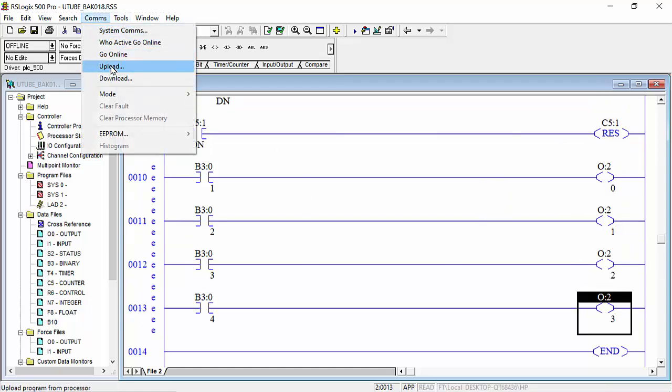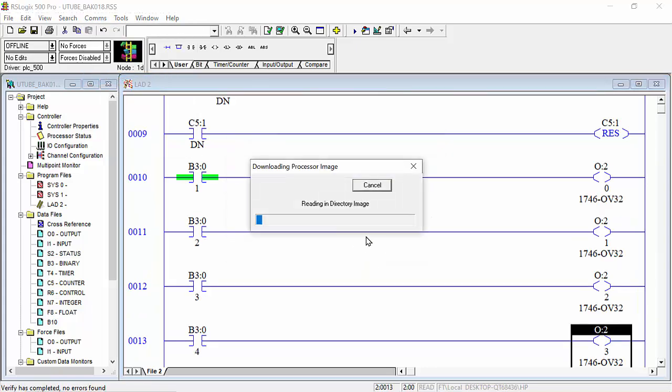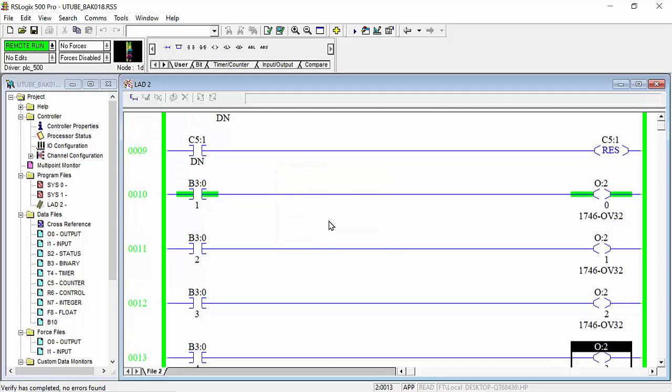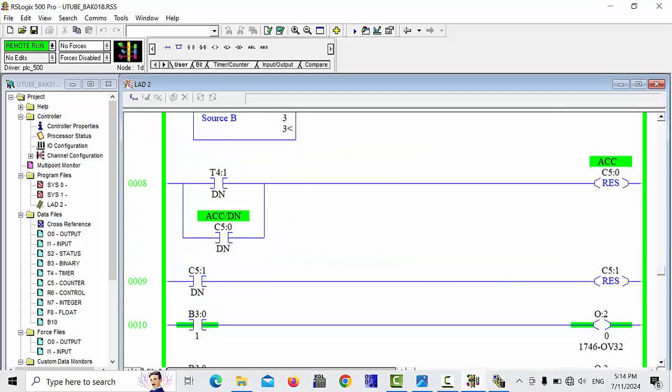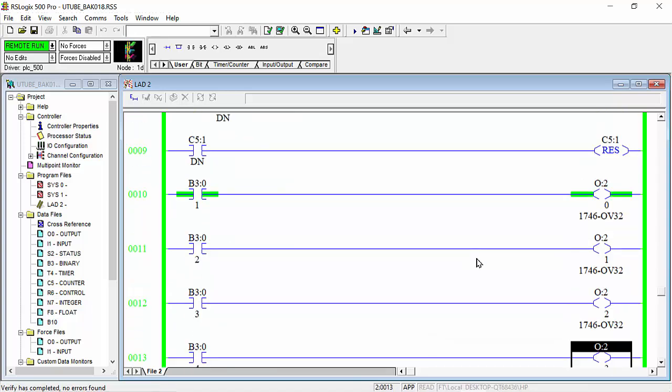And again download to the PLC, and this is your final address, that is, the output of your PLC. Here you can fix your output, any contactor or whatever, and make the execution on. Now your output is on, first bit O:2/0 is on. Now when the time is finished, after that your second bit will be on.